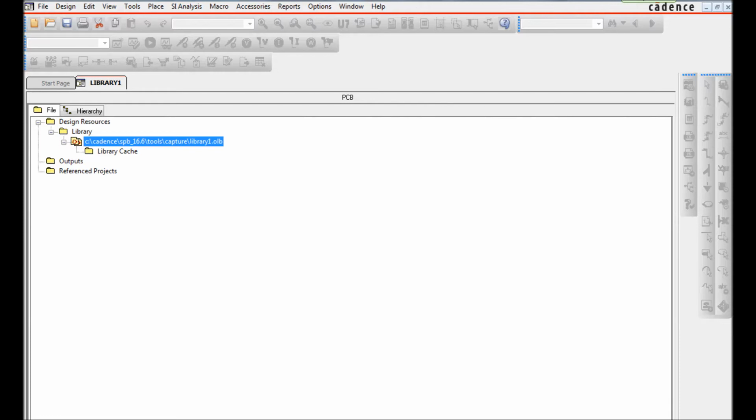So what I'm going to do is rename the library. In the Project Manager window, click on the library file, library n.olb. What I have here is library1.olb, but I'll be renaming this by clicking the letter N. So here, if you see it says library1.olb, that was what I meant by it earlier. And if there was just library, what I'd want to do is rename it.